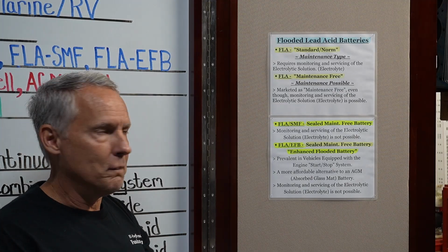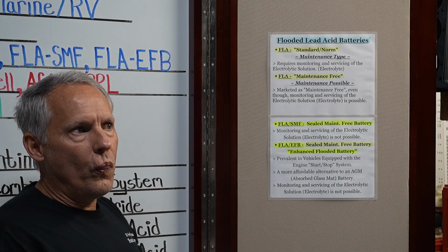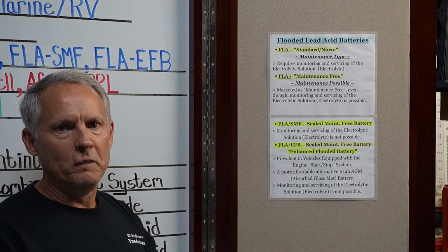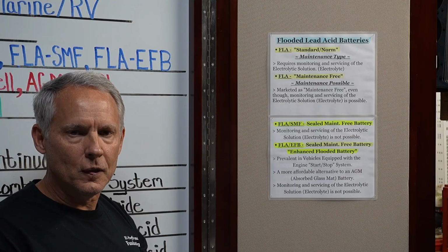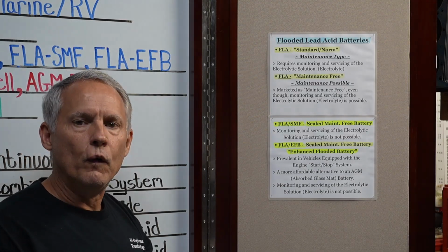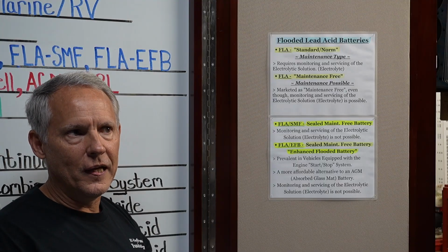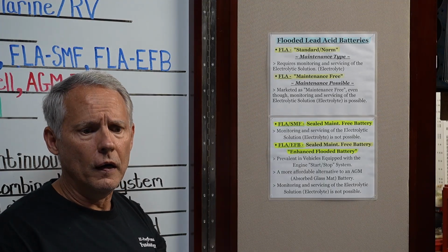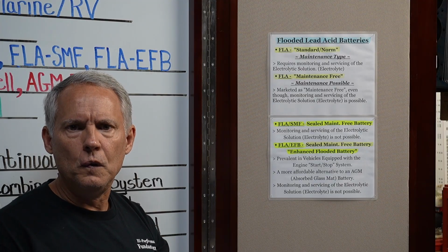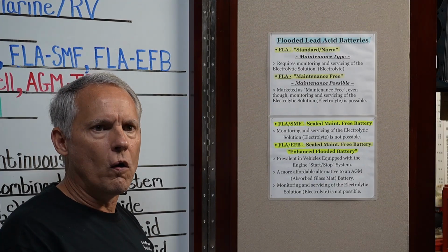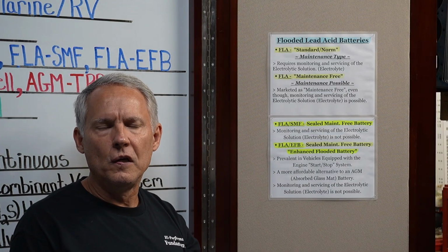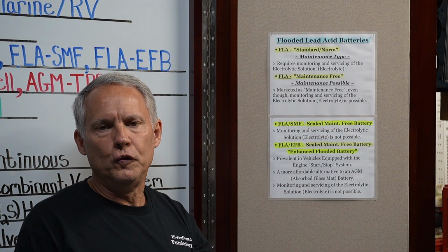But those batteries, the maintenance type batteries, what ruins them the most, or what they suffer from the most, is lack of maintenance. When people do maintain them properly, they can last a very long time. But unfortunately, they don't get maintenance. They get neglected. Especially these days, a lot of your younger technicians are not really accustomed to maintenance type batteries, because so many cars now come with AGM or EFB or sealed type batteries that can't be maintained, that they're not used to doing it.